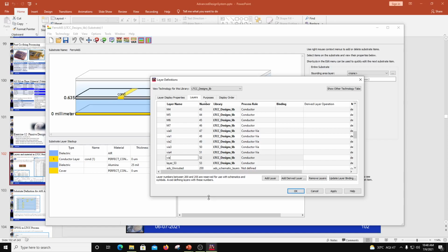So how would you get a 3D drawn from a 2D simulator? What you do is you define different layers, metals, vias, and then when you draw on those layers, that is interpreted as if it has got a dimension in the z-axis, right? So via 4, via 5, conductor via, and then via 6.